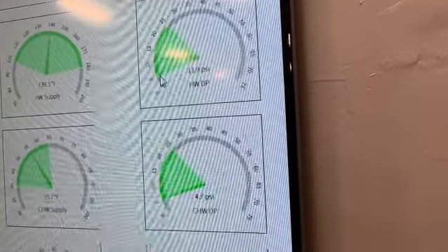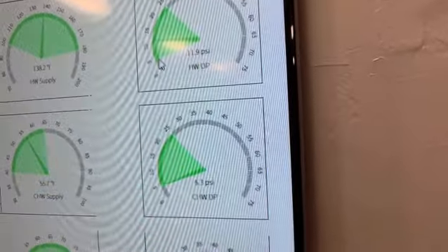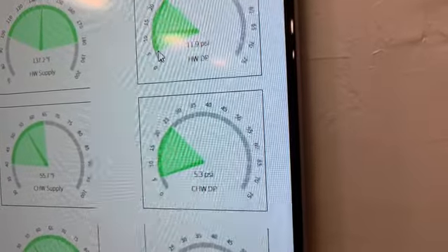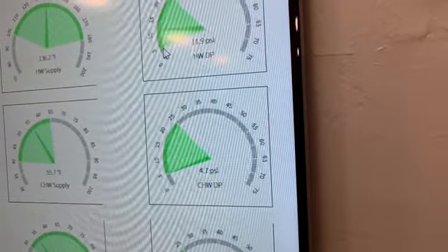It's a sensor with a hose or a little pipe on the supply side, and another hose on the return side. And in between them, you're gonna have a sensor measuring the difference. So if the difference drops, it will increase the speed.